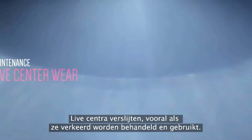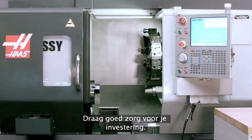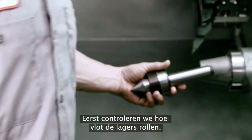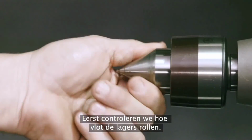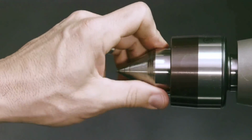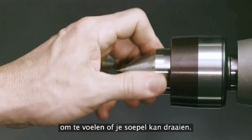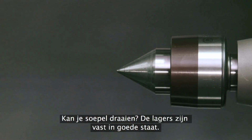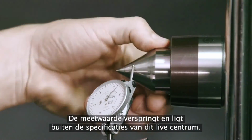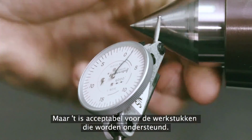Live centers do wear out, especially if they are mistreated or abused, so take good care of your investment. Let's check the condition of this used center. First, we're going to check out how smoothly the bearings roll. Rotate the tip 4 revolutions, and then keep rotating in that same direction, feeling for smoothness of rotation. If it's smooth, the bearings are likely in good condition. Next, let's check the runout at the tip. The reading is a little jumpy and it's above this live center's specifications, but it's still acceptable for the parts